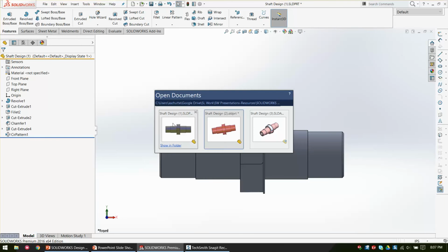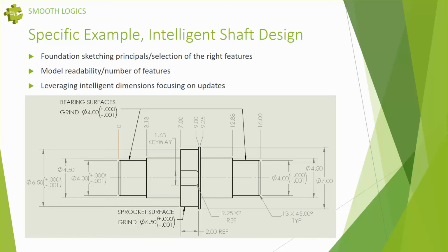And we can see, not what I wanted, we can see on my PowerPoint how that pans out from a manufacturing print. The dimensions I put in the model have no bearing whatsoever on the dimensions I show on the print. I want to show on the print all of the diameters because that's what's important to the machinist. But as a CAD modeler, I only want to have the correct dimensions that drive design intent. And this is where collinear is a great example because I always want these bearing surfaces to be the same. So I would never want 2 dimensions in that instance.